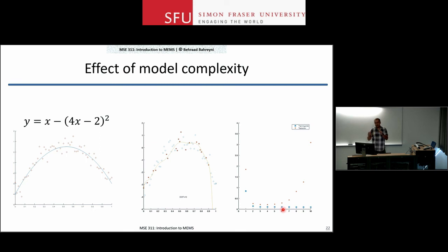Again, in engineering applications, go and use your engineering intuition. If you're looking at, let's say, a nonlinear phenomenon, such as electrostatic actuation, you saw that it was proportional to voltage squared. If you're fitting to that, keep V squared, V, and maybe a bias.